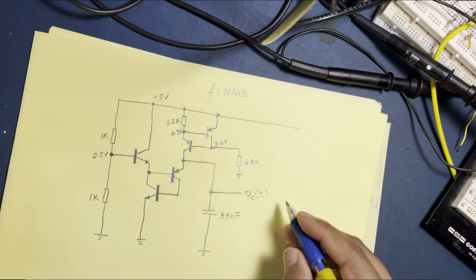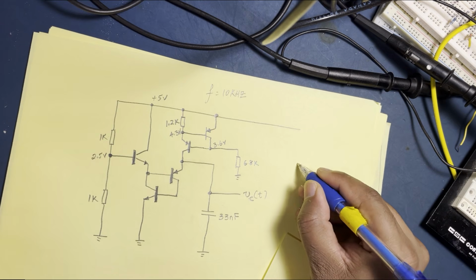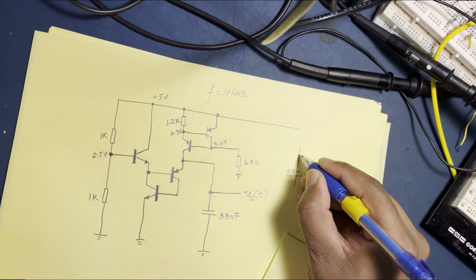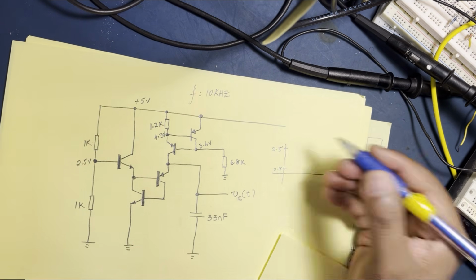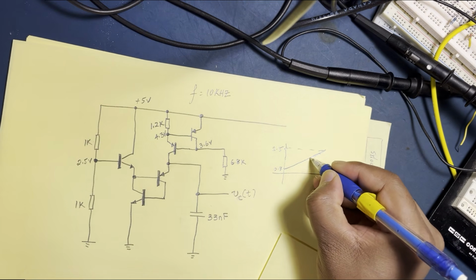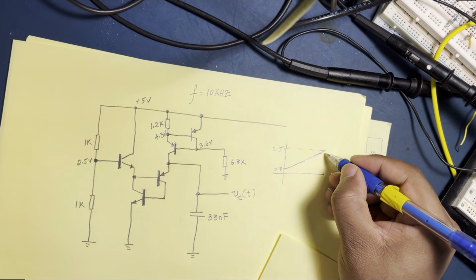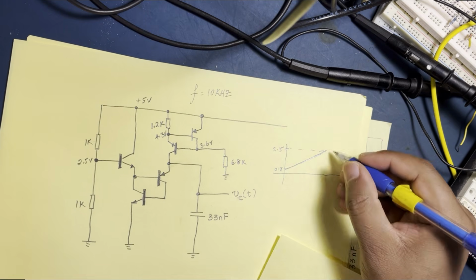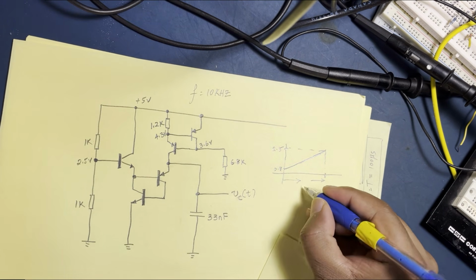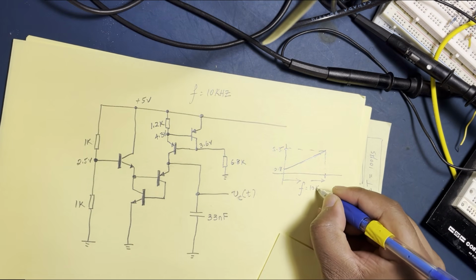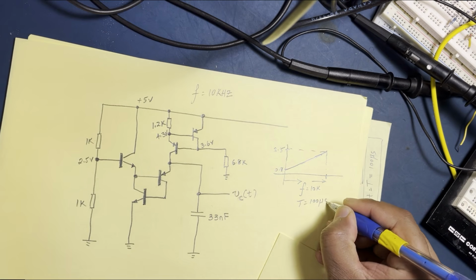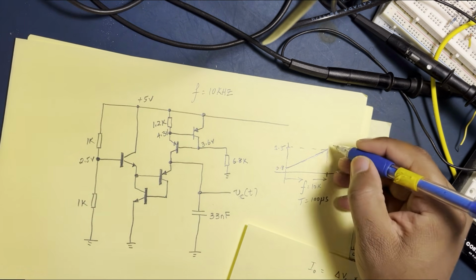2.5 volts, right? And then we're going to see this VC of t. We want to see it oscillate between 0.8 to about 2.5 volts, right? That's what we want. We want to see it ramp between 0.8 volts and 2.5 volts. And the time it takes to do that is a period of, or 10 kilohertz, right? Or a period of T equals, we calculated 100 microseconds, right? That's what we want to see, right?